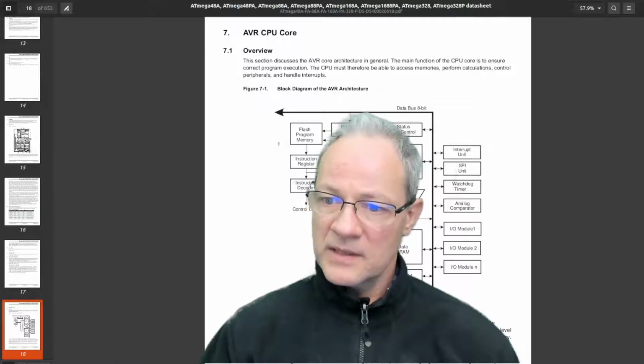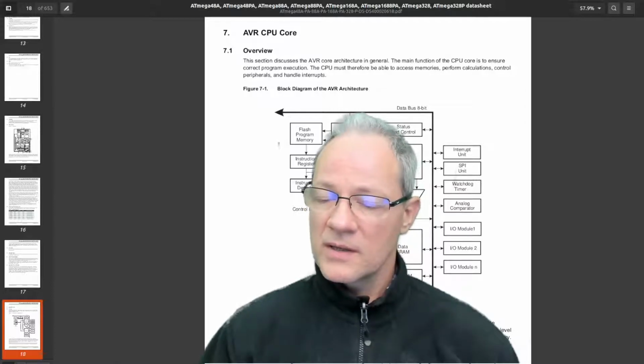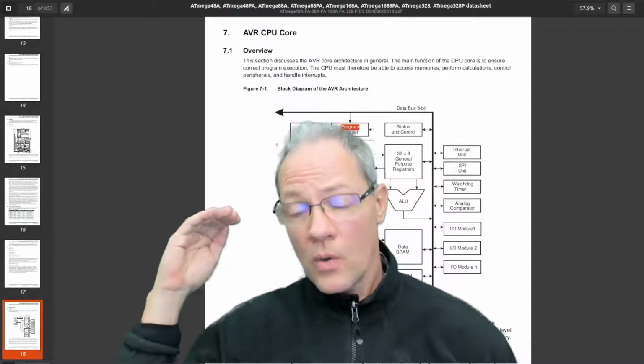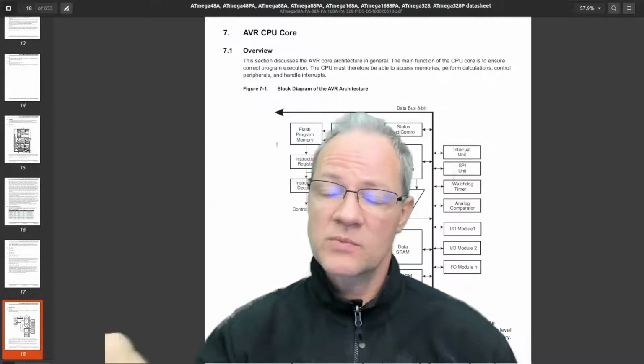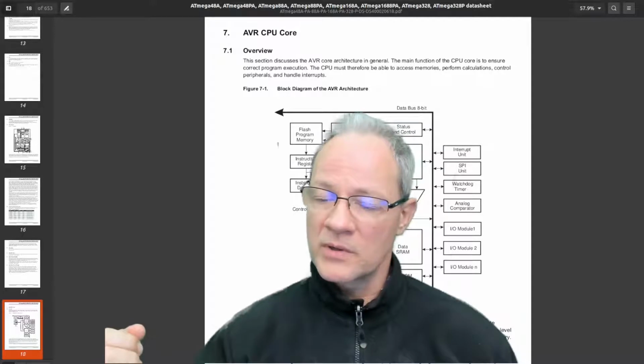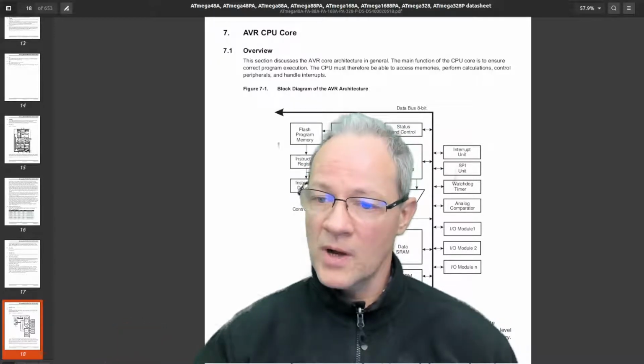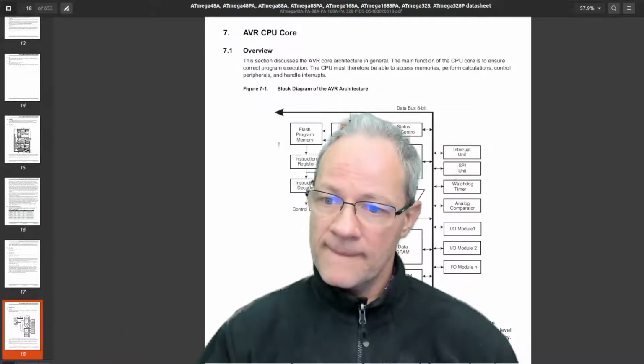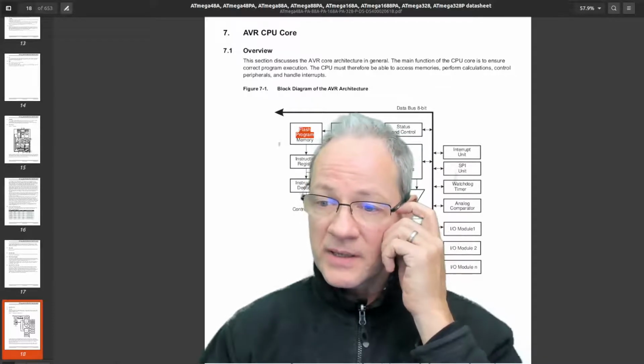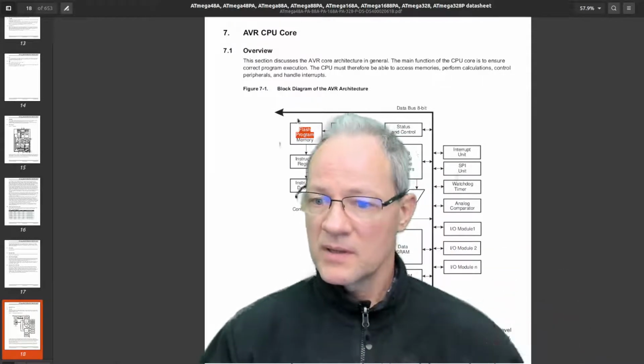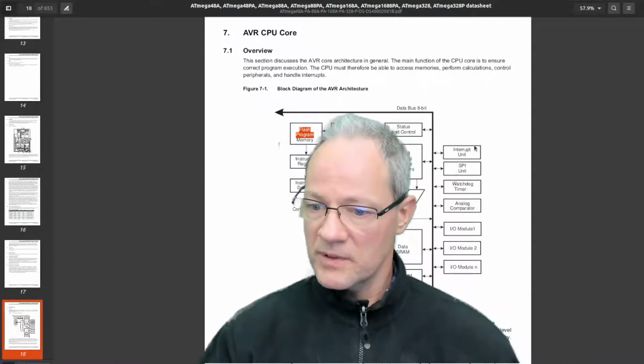Right. Then there is this program counter register, which points to the current instruction, just as we discussed in our class when we were doing the assembly programming for ARM processors. And the memory for the program is the flash program memory, right? So this architecture is different in a way that the program sits in one memory and the data sits in random access memory. The data is RAM here, right?